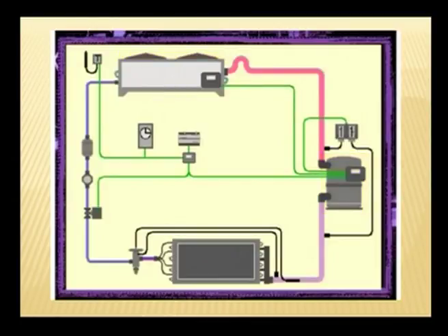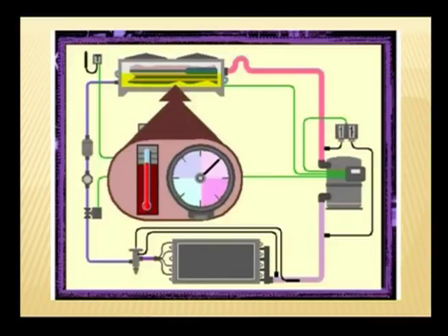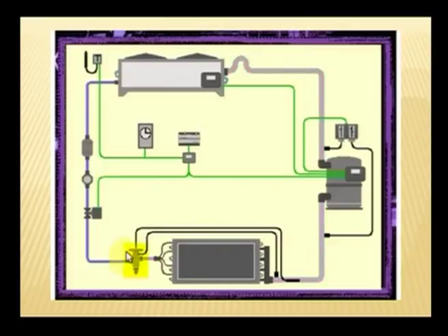The function of the inverted U trap located at the condenser inlet is to reduce the hammer effect caused by the sudden arrival of massive refrigerant in the condenser. This usually occurs when the compressor starts up. The inverted U trap also holds back the liquid refrigerant and prevents it from returning to the compressor when the compressor is off. The refrigerant reaches the bottom of the condenser as a liquid at high pressure and high temperature. As soon as this happens, it again passes through the expansion valve to re-enter the evaporator at the required temperature and pressure. The refrigeration cycle continues to operate as long as the room thermostat indicates that there is a need for cooling.